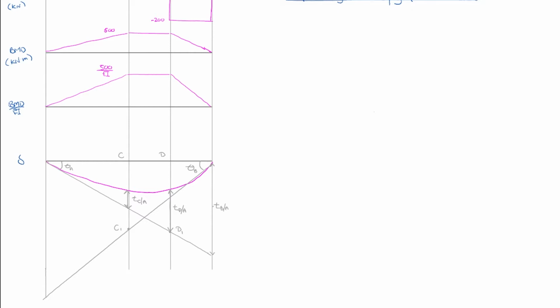As you're probably aware, the tangent distance at A with respect to B is actually this distance over here, and it clearly is bigger than the tangent distance at B with respect to A. So you want to make sure you get that right so that we don't make a mistake later on. But having identified that, we actually have all of the logic to solve the problem.